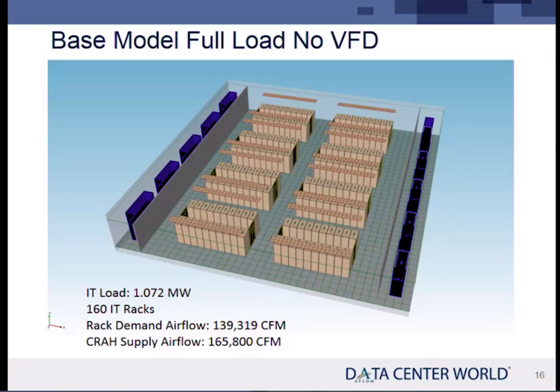The reason I point this one out is I've seen these perform pretty well. I've seen these kinds of data centers with that kind of design operate at a PUE of around 1.3, 1.25. Not too bad. And that's probably the most cost-effective solution you're going to get without going to full containment. And like I said, full containment starts to bring other issues in, pressure issues and airflow issues within the containment itself. This one has no issue. It's really convective hot air. The hot air is coming out the backside of those racks and we're using buoyancy in our favor here. It's floating up into the ceiling and being sucked out. Pretty nice design, low-cost design, economical.